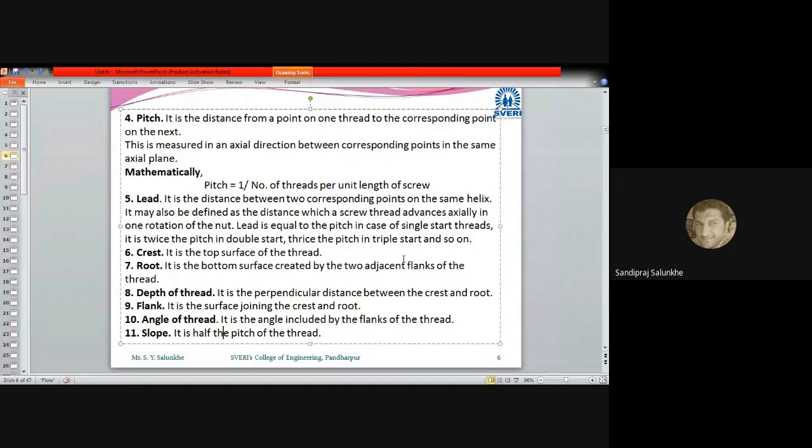A water bottle must open fast, whereas threads used in machinery should keep two parts together very tightly, and should not easily loosen under external load or vibration. That's why they take 2 turns to complete one thread, whereas a bottle requires half a turn to open.